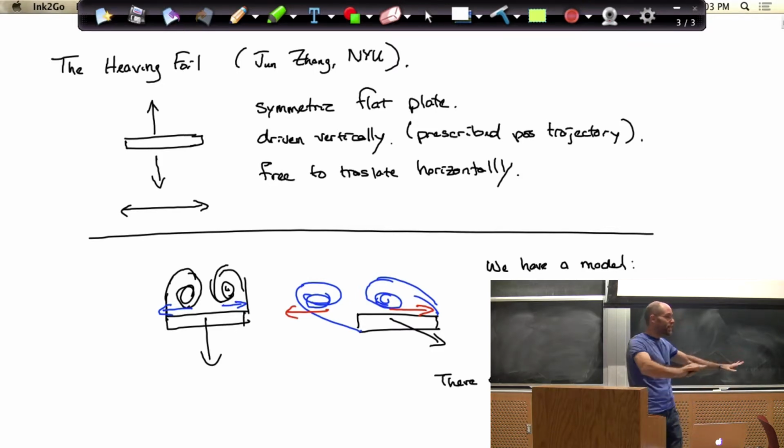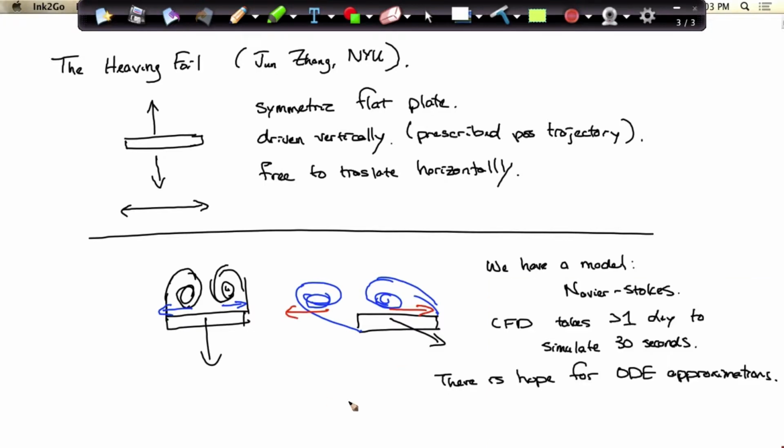You could trip the boundary layer and just have a different system there. Don't even pretend that that system is the same as that system. Those are completely different, right?" So that made me extremely paranoid about the sensitivity of the models that we have in fluid dynamics. Obviously, the airplane's going to, in net, do pretty similar things, but the details could be pretty different. Okay, so there's also a lot of sensitivity to geometry, to boundary conditions.